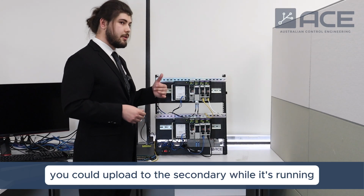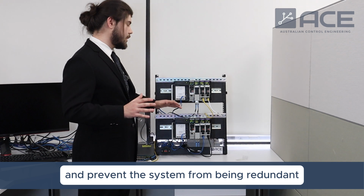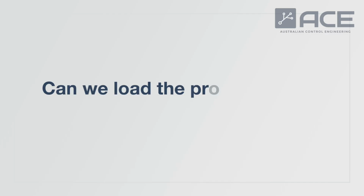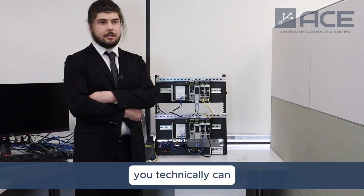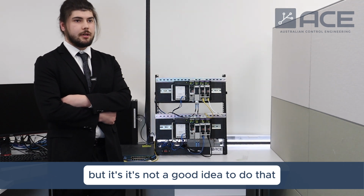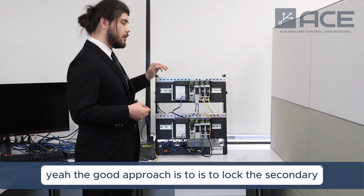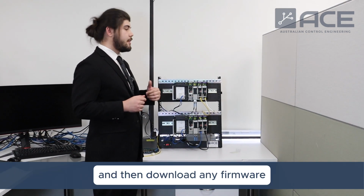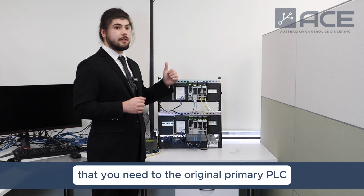Obviously, you could upload to the secondary while it's running. All it will do is immediately disqualify and prevent the system from being redundant. But that locked sequence is a way to do that more reliably. You technically can, but it's not a good idea to do that. That's why they have that functionality present. The good approach is to lock the secondary, download it to the secondary, perform that switchover, and then download any firmware that you need to the original primary PLC.